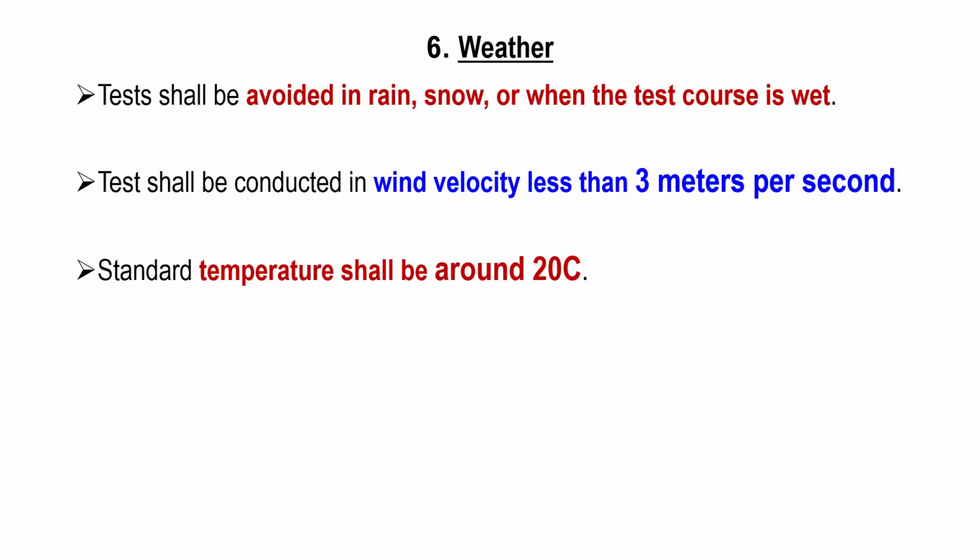Weather. The test shall be avoided in rain, snow, or when the test course is wet. The test shall be conducted while the wind velocity is less than 3 meters per second. The standard temperature for the test shall be around 20 degrees centigrade.